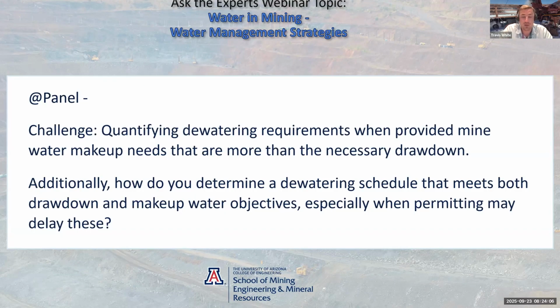So how you get around that, to maybe touch on the second part of the question, your dewatering schedule, you should kind of treat standalone. So that needs to be driven by the geotechnical and the mining or business requirements. And then you should find as many routes or options to augment your supply. So your makeup water can be anything from stormwater or surface water harvesting, capturing all your surface runoff, capturing glacial melt, snow melt, and the likes. Getting water from a well field offsite, getting water from a municipal or regional water scheme, and build in redundancy in that system, in all systems.